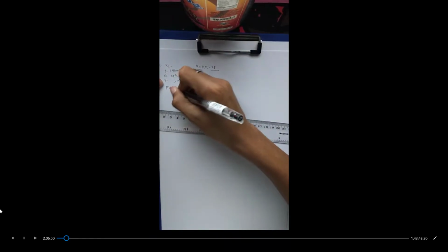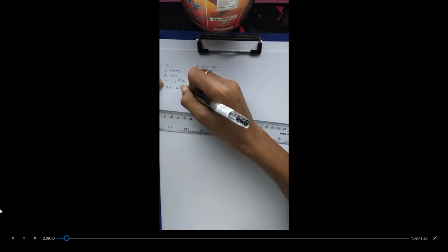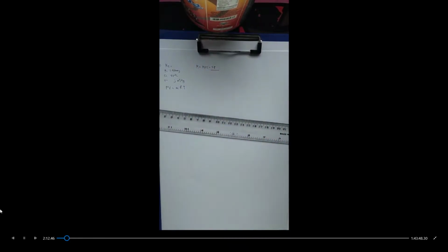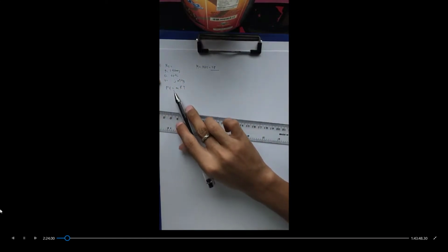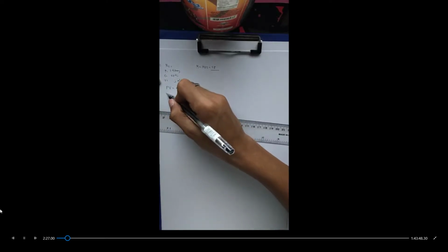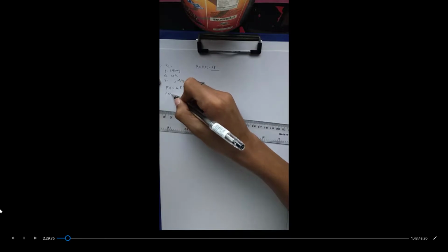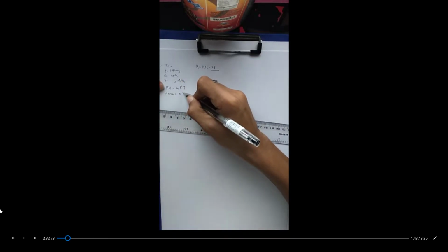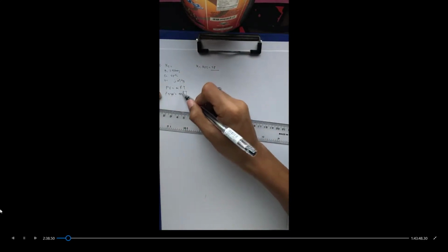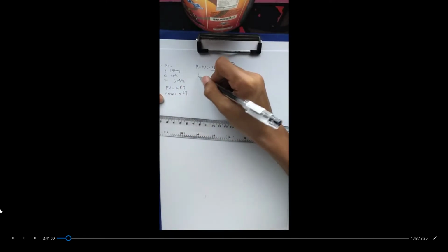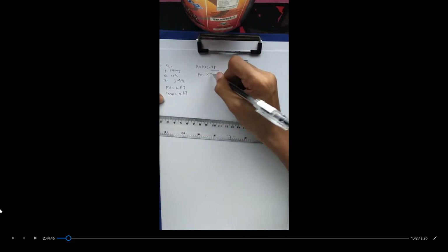So we will be using 28 as our molecular weight. Now let's start with our ideal gas equation, which is pressure times volume equals mass, the gas constant, times the temperature. Since mass is not specified and there's no way for us to solve for mass, we are going to factor out mass. In the left side, the pressure volume becomes pressure times specific volume times mass, equivalent to mass, the gas constant, times its temperature. Then by dividing mass on both sides, our equation now becomes pressure times specific volume equals R times T.